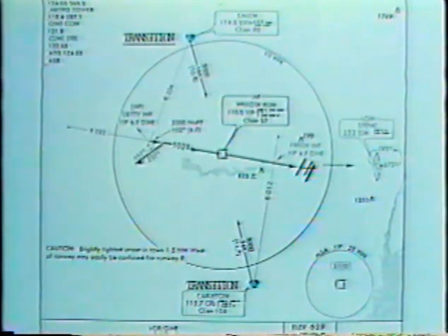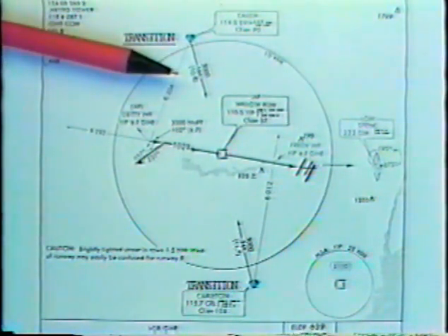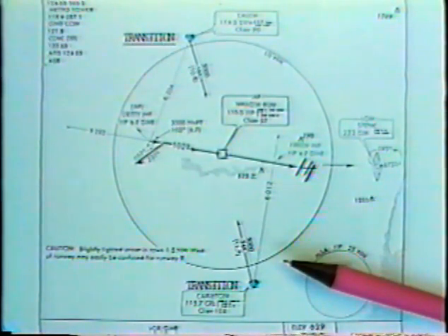Cleared for approach. This clearance authorizes you to fly the procedure on the approach plate and to descend to the published altitudes. You may not descend during an approach until you have received approach clearance and are on a published route. The published route may be any approach segment, transition, or airway. If an airway, you may descend to the MEA, but be sure it is higher than the transition or initial approach altitude. Otherwise, you will find yourself climbing later on. When flying direct to an approach fix, you may not descend even if cleared for approach until you are on a published route.